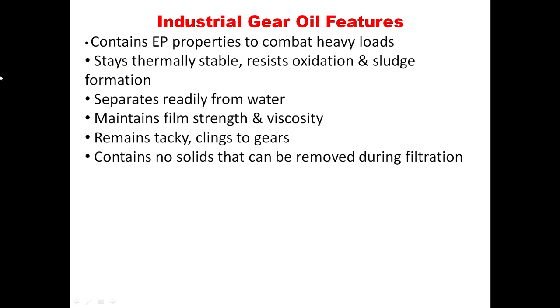Industrial gear oil features: contains extreme pressure properties to combat heavy loads, is thermally stable, resists oxidation and sludge formation, separates freely from water, maintains film strength and viscosity, remains tacky, cleans and protects against wear, and contains no solids that can be removed during filtration.